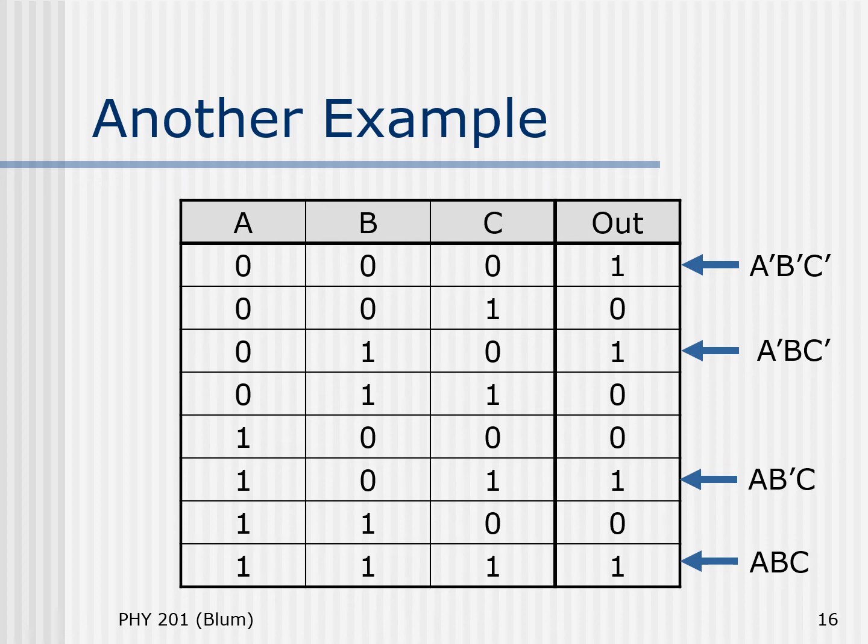And we're going to focus on this approach. We focus on the ones, so we pick out the ones with the blue arrows. We will ignore the zeros and focus on the ones. And then we will write the expression for those ones. So the top expression is A prime, B prime, C prime. And you can see that we're focusing on ones, and then we write the expression that sort of forces that row to be a 1. So if A is 0, B is 0, and C is 0, and we want a 1, then we invert A and invert B and invert C so that we get all ones.